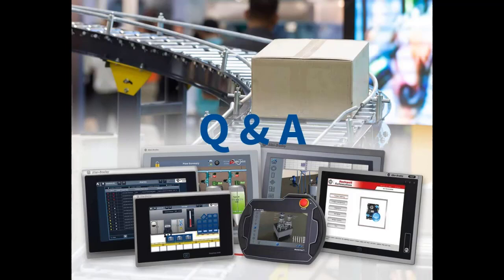You're allowed to log up to 6 data points. And you can only log from one trend object, so you can't set up multiple trends. And one other point, if you want to log continuously, there is a checkbox you need to select so that it'll log when that trend object isn't on the screen. Otherwise, it'll only log when that trend object is on.